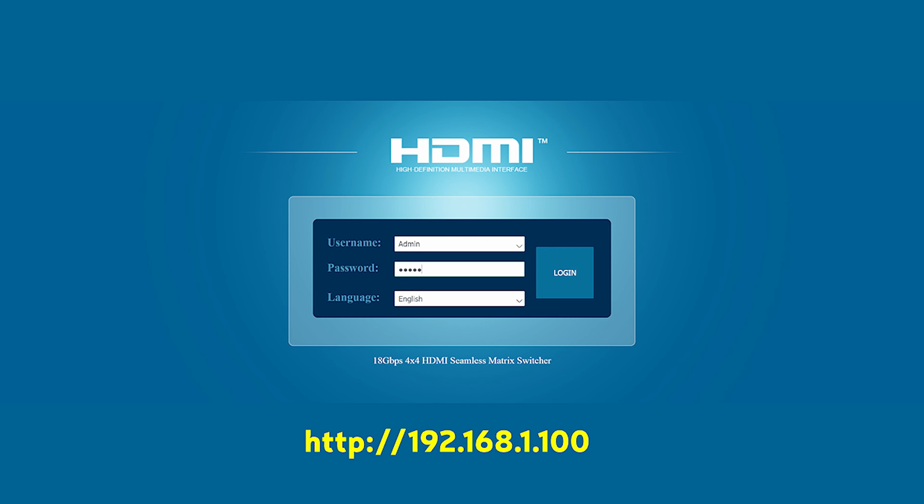When you open a browser and navigate to the device at IP address 192.168.1.100, you'll see the login screen. Here, you can enter your username and password. The default username is admin with a capital A, and the password is again admin, but this time with a lowercase a. You can also choose your preferred language. Once your credentials have been entered, simply tap the login button to enter the configuration options.